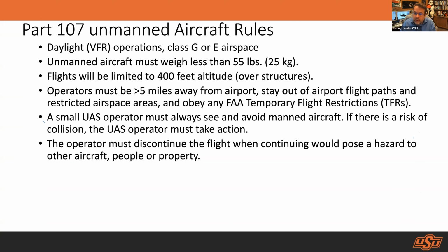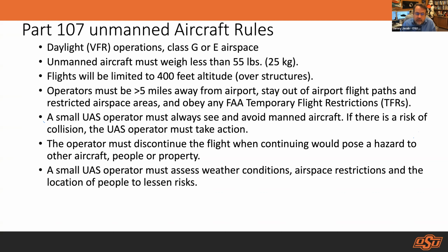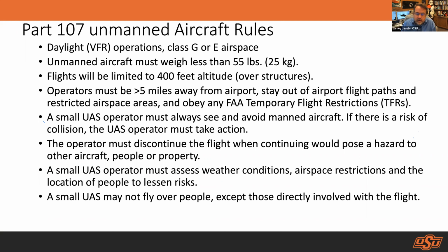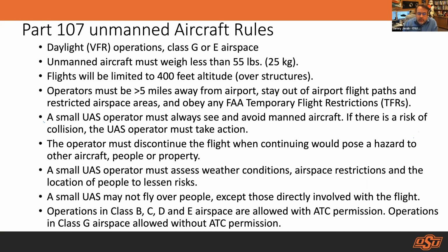If something's happening with the aircraft or appears there's some kind of malfunction, you need to be able to take immediate action and land that aircraft. You must also assess weather conditions, other airspace restrictions, and location of people to minimize potential risk to those on the ground. And you may not fly over people except those directly involved with the flight, meaning you can't fly over a crowd.